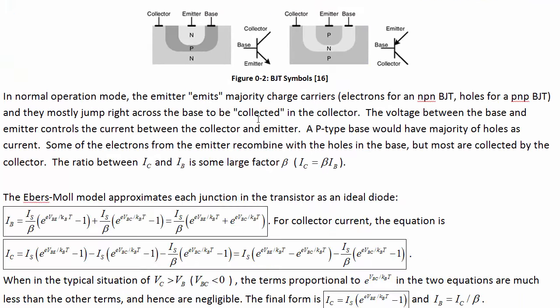Now, if you were to make this plot again, but instead of plotting base current in the background and then collector emitter voltage and collector current, you were to just plot the two voltages, you can reimagine the two regions. So the saturation region is when we've got large enough VBE and very large base voltage relative to the collector.